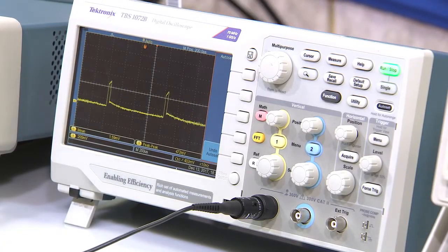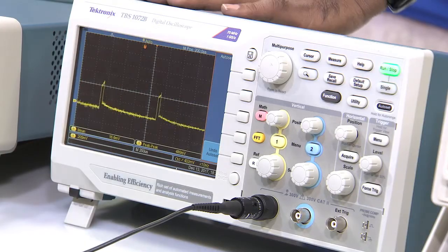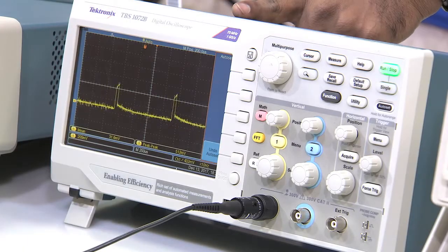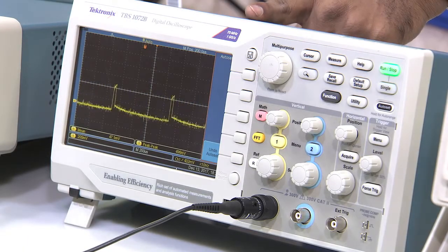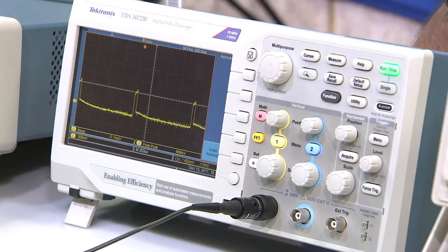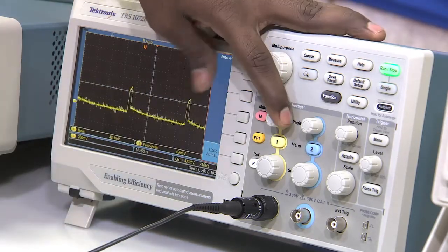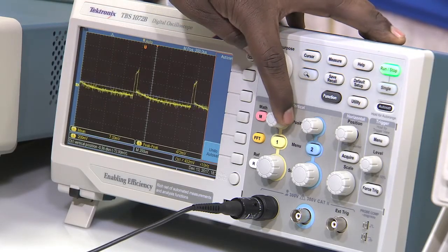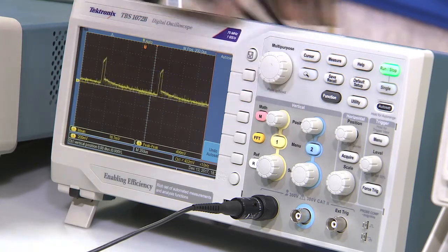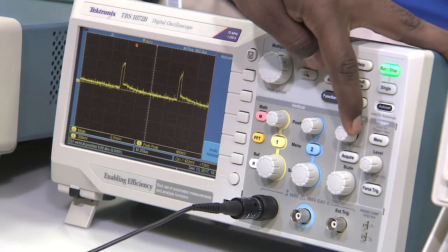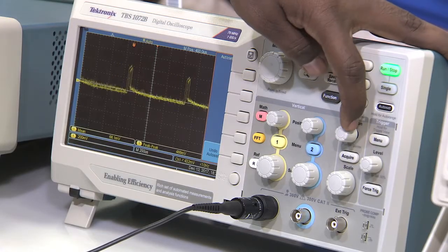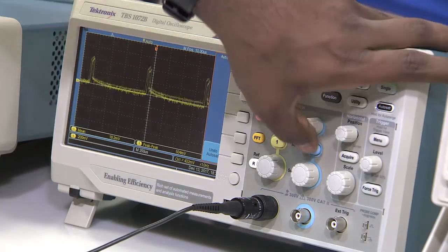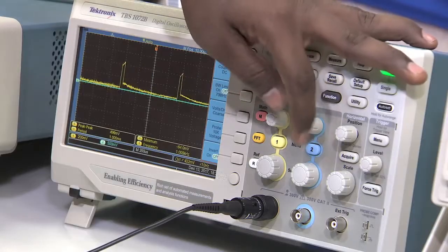Now, you see there are two channels like we have discussed, right. Channel 1 yellow color, channel 2 blue color. These knobs for channel 1 and channel 2 are used for changing the vertical position. Right now it is connected to channel 1, right. So, can you please change the vertical position? Excellent. You are looking at the y axis, look at the y axis, it is changing, right. Can you change the horizontal position please? Horizontal position, very good. So, you can change the horizontal and the vertical positions, this is nice. Now, similarly for channel 2, but right now channel 2 has no signal.